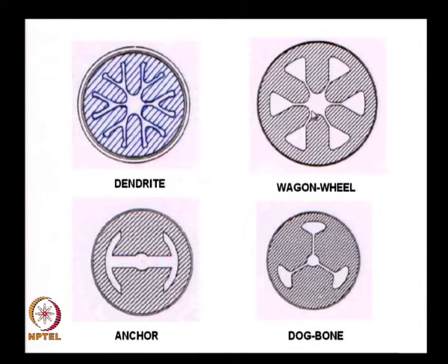You have a wagon wheel, in the shape of the wheel of a wagon. See, you have the inner surface which is like this, and the length of this is along this particular direction. Therefore, the perimeter along this is now quite large compared to what it would have been for a circular diameter over here, multiplied by the length is what gives me the burning surface area, and this is known as a wagon wheel. I could have different shapes, any possible shapes.